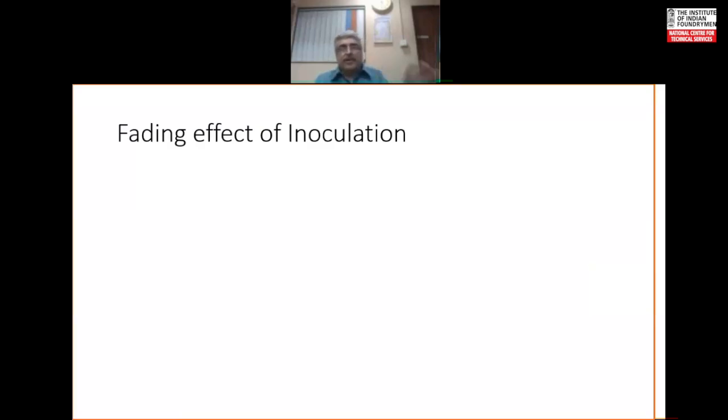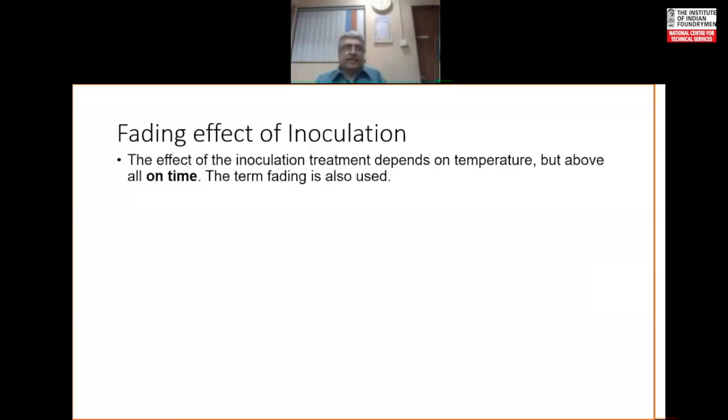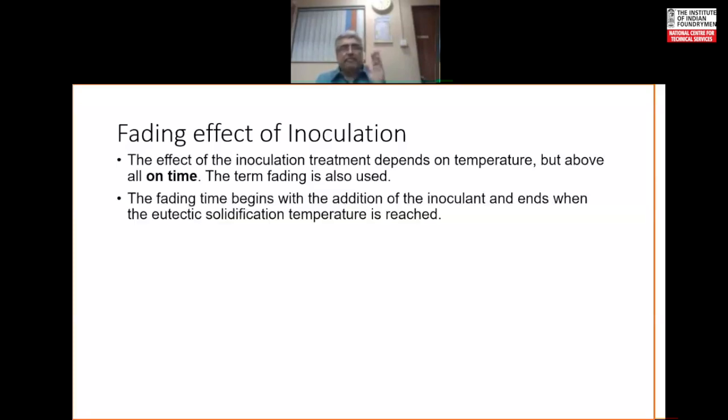It depends on the treatment temperature, but most of all on the time for which they are present in the melt. This changing effect of the inoculating materials is called fading of the inoculation. The fade time begins when you have just added the inoculant, and it ends when the eutectic solidification temperature is reached.